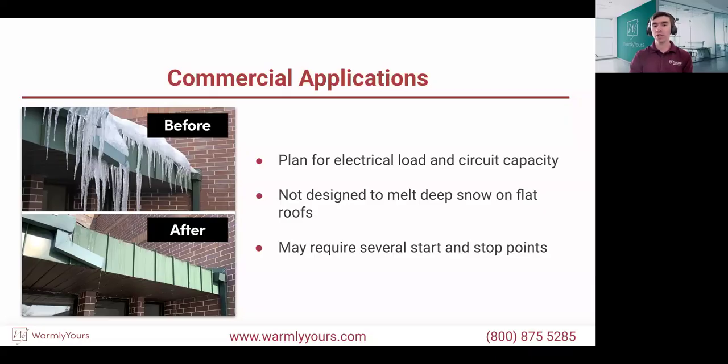Let's say we did this basic estimation and we know we definitely need at least 3 or 4 circuits. That would be a great input to share with the electrician and understand where those 3 or 4 start points may be. At this point, we will create a good layout that makes the whole installation and planning simple.